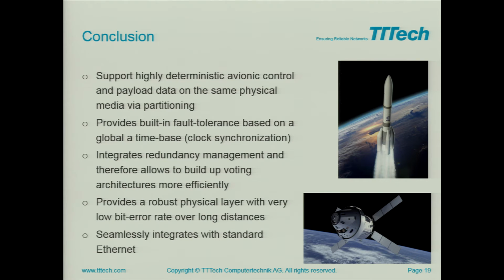Good, for my conclusion, I want to summarize a little. The network is capable of highly deterministic avionics, with full determinism and fault tolerance. It can also be used for payload data, and the speed is quite good. It goes up to 1 gigabit, and the component can fully support that.